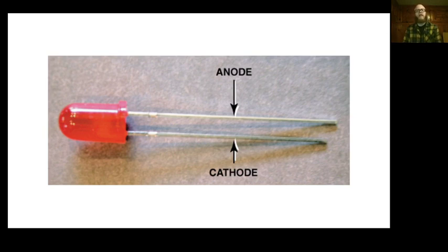An LED, when we're passing current through it, some of that electrical energy gets turned into light energy, into photons, and then the semiconductor material lights up because it's fancy, and we get light out of it. And this requires way less current than a light bulb, because a light bulb turns electrical energy into heat energy that heats up the filament to the point that it's glowing, and then that produces light. So we waste a lot of the energy with heat. We just skip the middleman and go straight to light energy: LED.